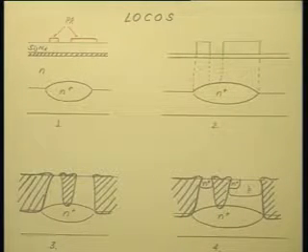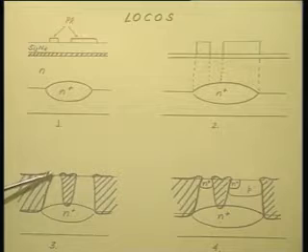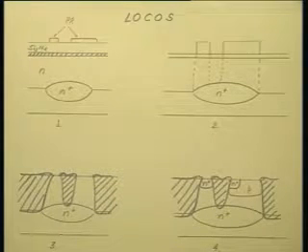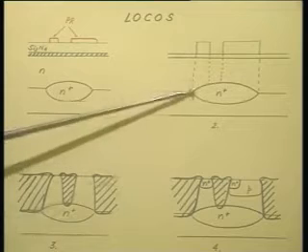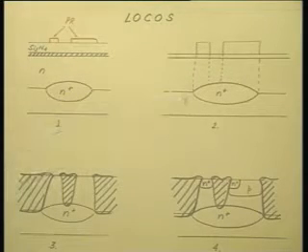But of course, if you do this recessing, then you have a slight non-planarity on the surface, which is caused because of lateral oxidation. See, when you are etching it down, two surfaces are exposed, one is the horizontal surface and the other is the side wall.